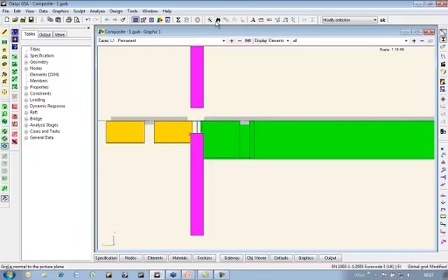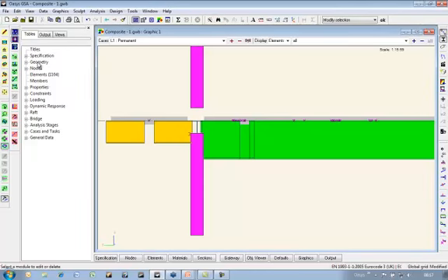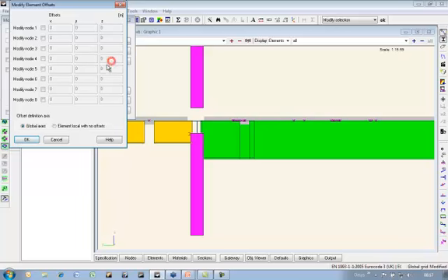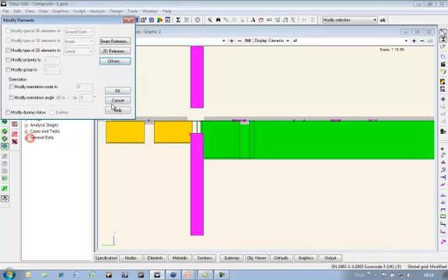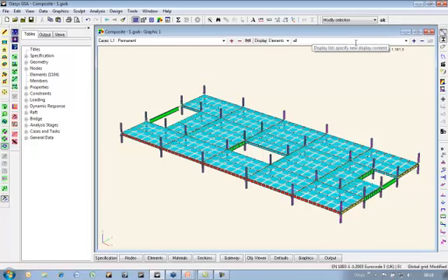I now need to select all the slabs. I'll use the find command for this, because I happen to know their property is area 1, and they are 160 thick. So I'll just modify those, apply offsets, and offset them up half a thickness, so 0.08. Copy that. Okay, wonderful, that looks good. Right, so offset done.